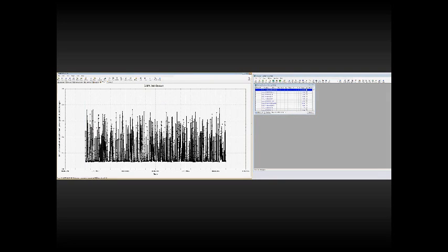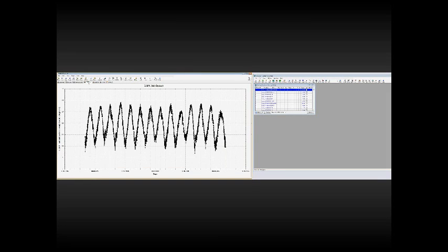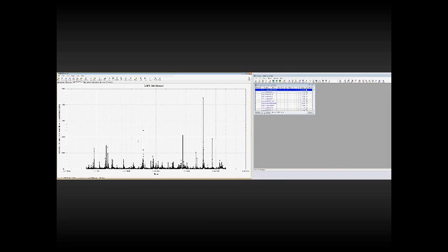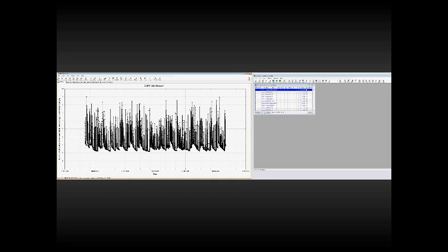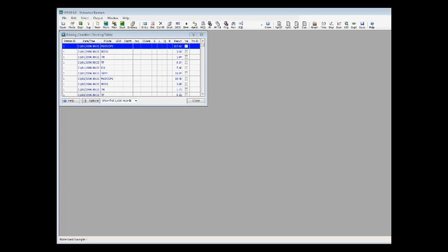So here is the total phosphorus for our simulation period, total nitrogen, water temperature, the flow, and we can see that we've had large periods of time where we had large rainfall, dissolved oxygen, and BOD. So we can see real quickly in a time series graph what our model results look like. The Water Resources Database is an excellent tool for processing these large amounts of time series data and summarizing them. You can use the graphics utility to do publication quality graphs. You can use the reports to give summaries of what was predicted by the watershed model.